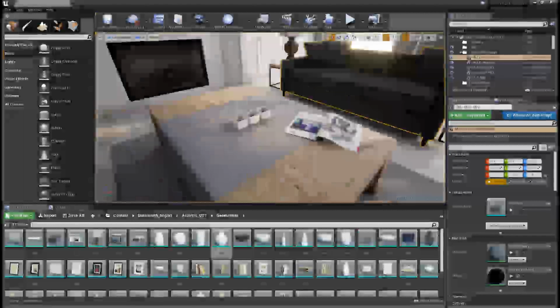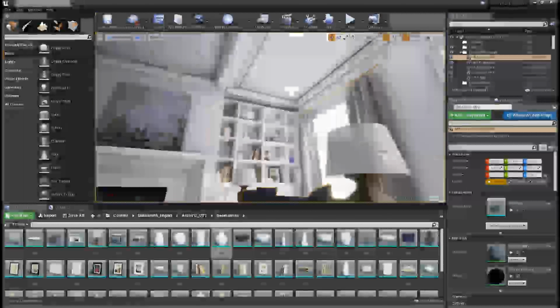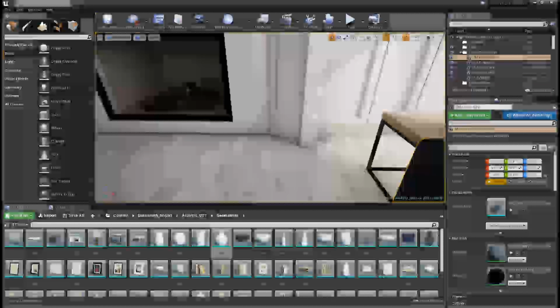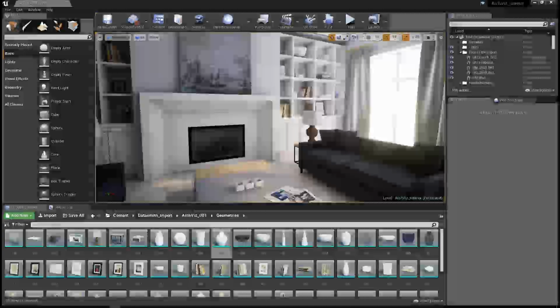And that human intuition will come into play here. Obviously, you need to move around your level and just make sure all the light maps look clean and they don't have any blocky appearance and whatnot. Baked GI light maps make your real-time walkthroughs look fantastic, but spending a little extra time creating custom light map UVs rather than relying on auto-generated UVs in every case will add the extra high polish to your lighting.